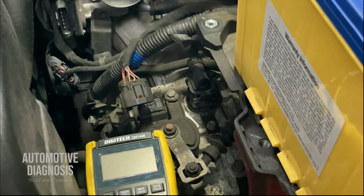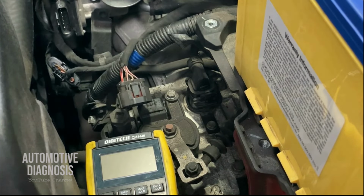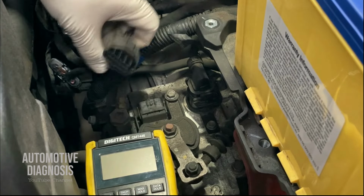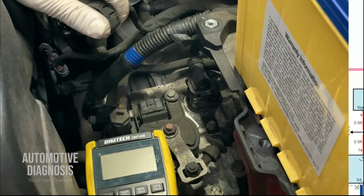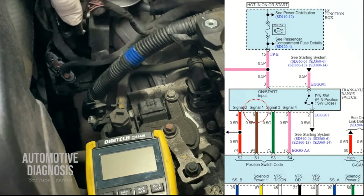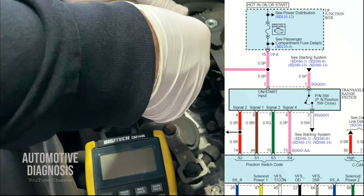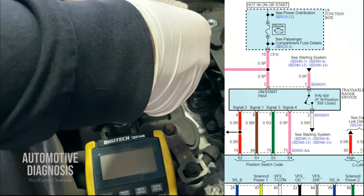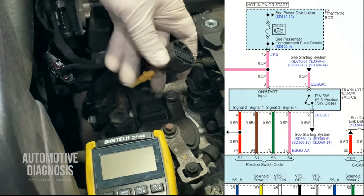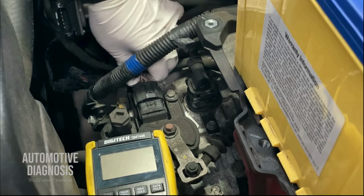For example, right now, I need to back probe these ones because I need to put the connector back when I'm performing the test. So the first thing is signal 1. And as you see on the screen, signal 1 is the brown wire number 8. So here's the brown wire number 8. I'm gonna back probe this. Okay, I did back probe it. I need to put it back on the range switch.